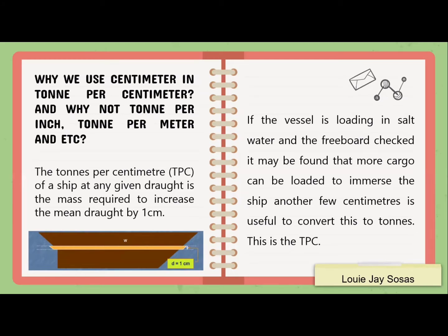As we all know, the TPC varies with the draft and with the water density. The densities of saltwater and freshwater will be explained later by the other members. Also, changes in draft cause a change in displacement, and the TPC assists in calculating the change. Next slide, please.